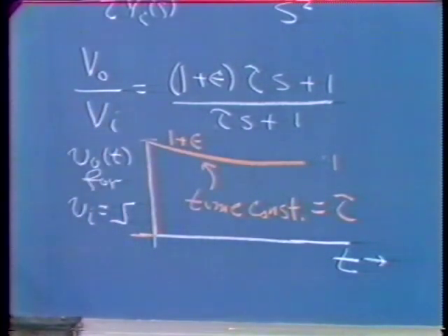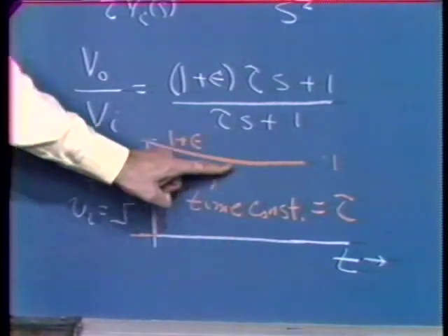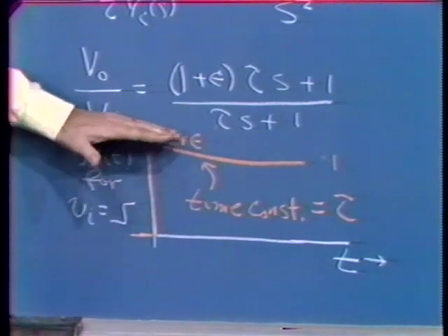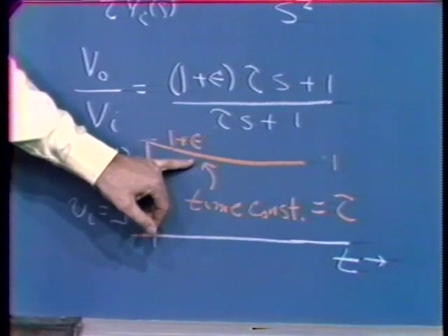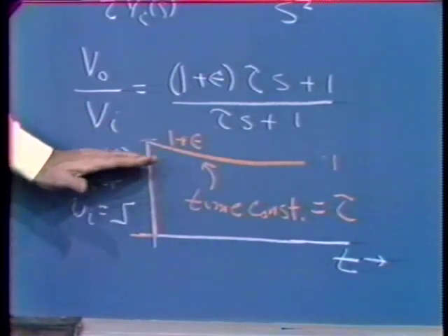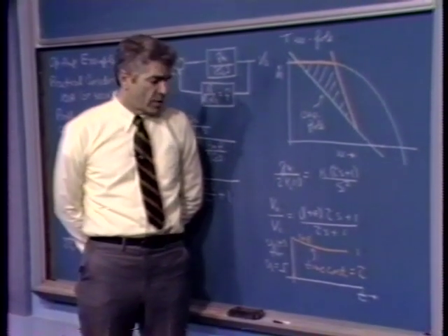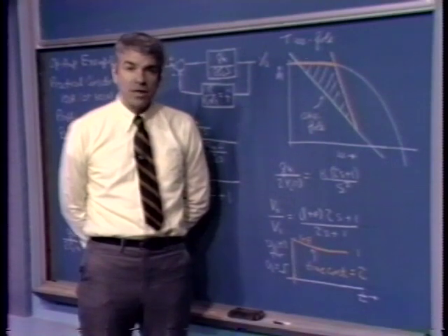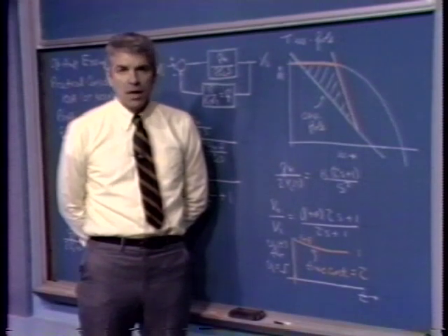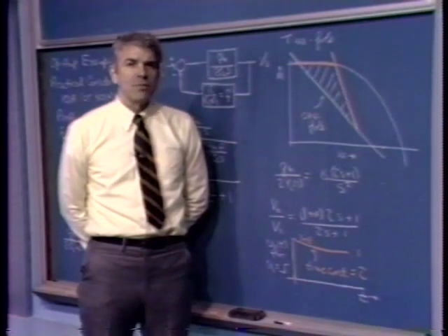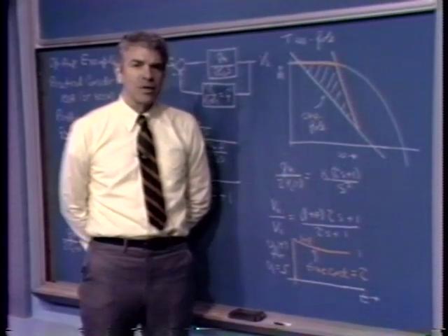the dominant pole pair. And so what we see is the high frequency response, the overshoot if you will, as the dominant response, but there's a long tail that reflects the much longer time constant associated with the pole of the pole-0 doublet. And that sort of thing happens, as I say, with lag compensation as well as with two-pole compensation when we do feedback compensation. And so one of the disadvantages of this sort of compensation may be that if we are really concerned about settling to a very small fraction of final value, that settling time may be compromised.